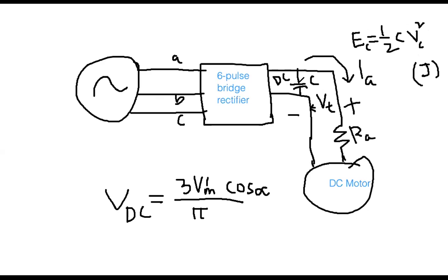This means that if you know the voltage across the capacitor, which is the same voltage, this VT, or the DC voltage that is coming from the AC side. This side is AC, and this side is your DC. That voltage appears across here. And if you know the energy storage capacity, then you can calculate the C value. Everybody, could you follow me?